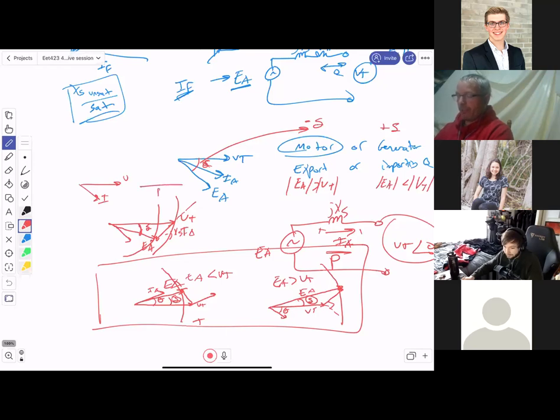My power triangle gives me a P and a Q that's both positive. So if it's a lagging power factor, whatever direction P is in, whether it's in or out, Q is in the same direction. So P is in for a motor, it's out for a generator, so Q is out, if it's a lagging power factor.